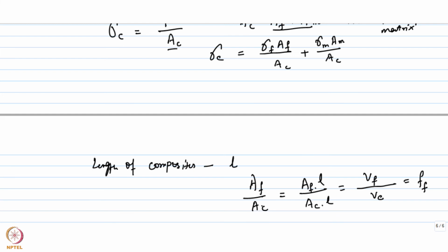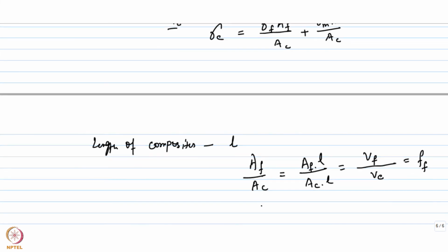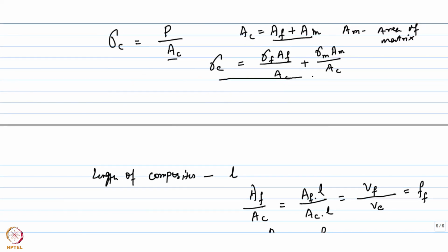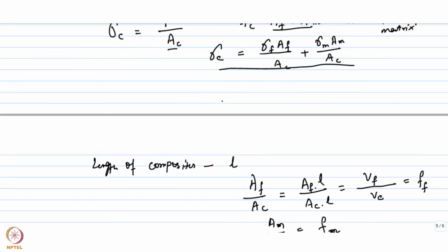Similarly, AM by AC will represent the volume fraction of the matrix. Okay. So from this, now we can rewrite this particular equation in terms of the volume fractions.